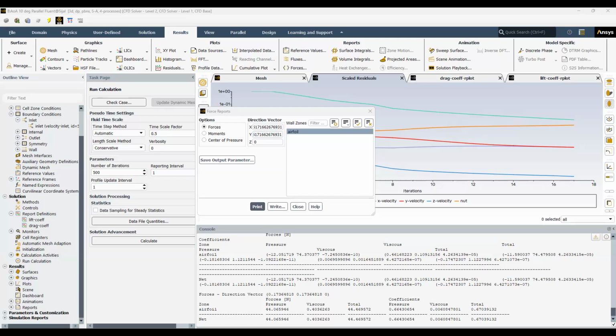Okay, now just take the example of the second case, the lift coefficient. So the lift coefficient is defined on this side. Okay, so the positive y-axis is here. It's a lift. And the positive x-axis is here. Okay, so in this case definitely we are going to resolve the lift coefficient into two components. One will be the y component, one will be the x component. The x component goes this way because it will be on this side. So this is our y component, this is our x component. Okay, now we have the angle of attack here with the x-axis, 10 degrees.